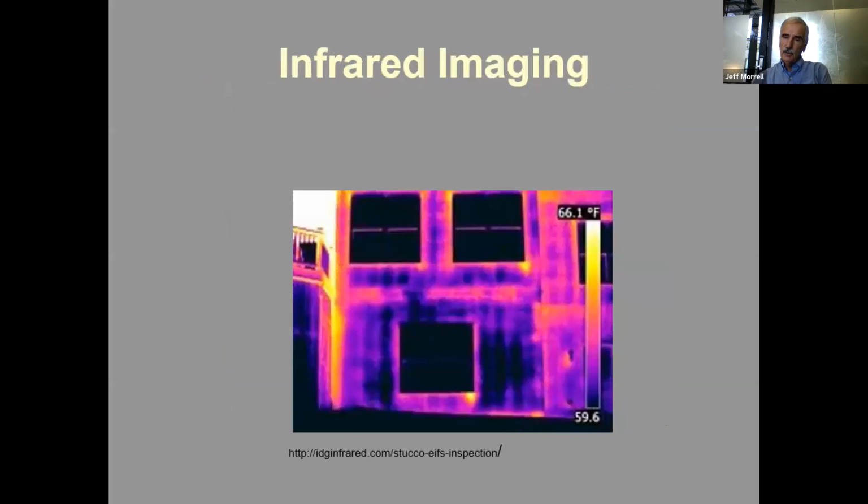And there's a lot of work going on in structures looking at infrared imaging, because you're not going to detect decay, but you can look at places where the wood is wet. So wherever the moisture tends to collect, that wood will change temperature more slowly than the wood on other parts of it. And you can look at the windows there and see at the bottom right-hand corner of two of those windows, the temperature is higher, and therefore you've got moisture there. You may not have decay, but it tells you that's an area where you should be looking.